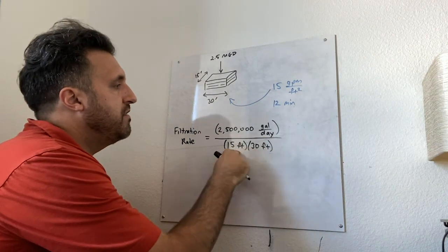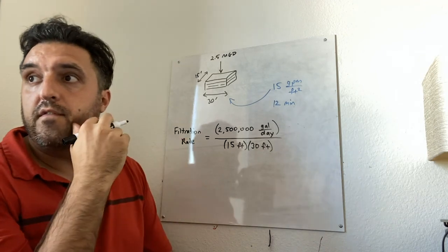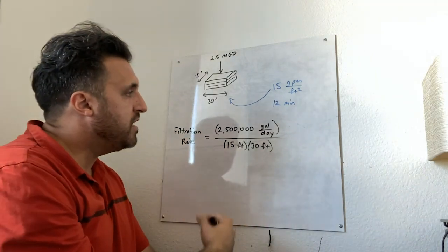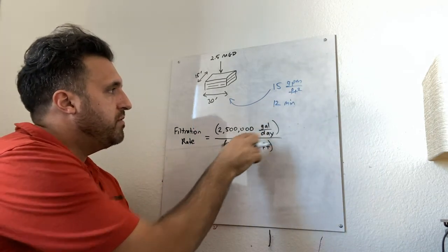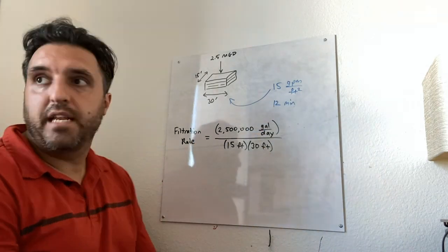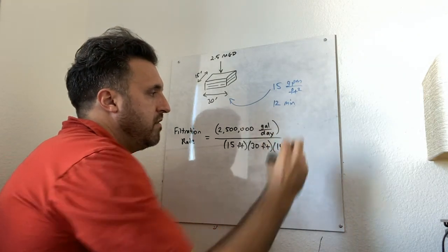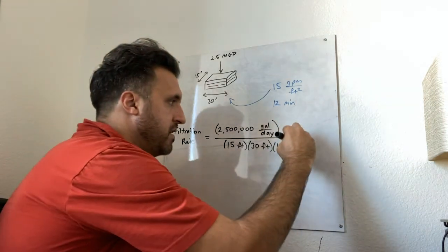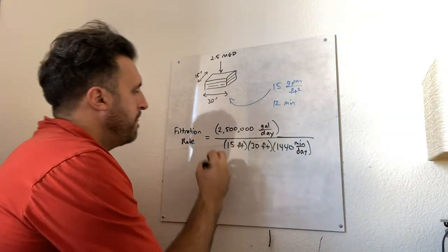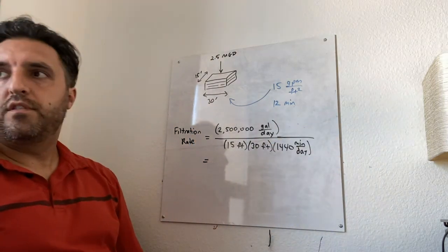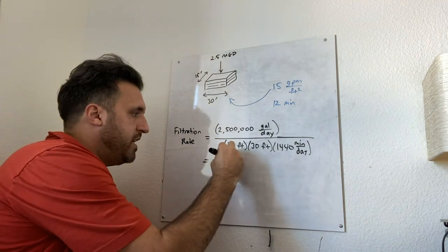Alright, so we'll need to convert gallons to, well, we can keep it actually in the units gallons per minute per feet squared, just like the backwashing rate. But we will want to convert days to minutes, so we'll add down here 1440 minutes per day in the denominator. And if we do that calculation, we get a filtration rate of 3.9 gallons per minute